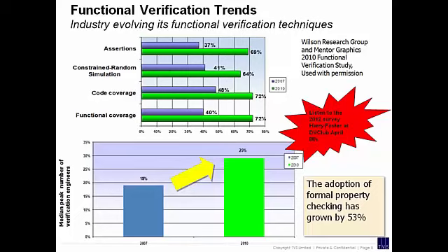The reason they do that is, if you're trying to find a bug in your code, I always think there are two things that happen. One is the difference in time. So if you have a bug, and when you're doing verification, you find a bug. You don't find the bug, you find the implication of the bug. So your test fails because of this bug, but it doesn't fail immediately. It can fail 1 cycle later, 10 cycles later, 100 cycles later, maybe 1,000 cycles later. And that time gap will have a big factor on how easy it is to debug. Okay? And then if you look at your code space,